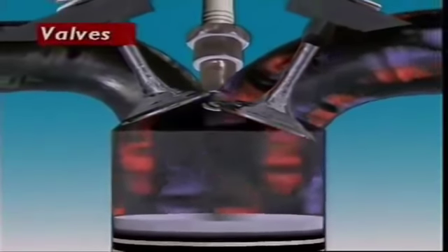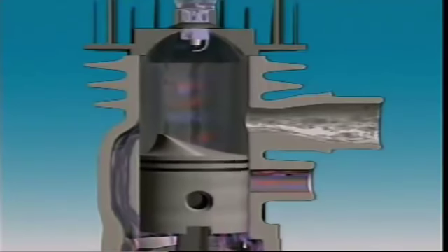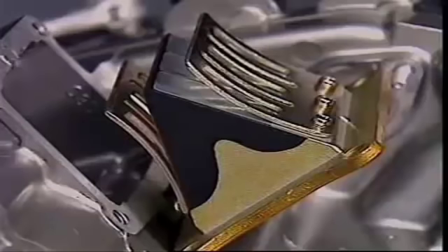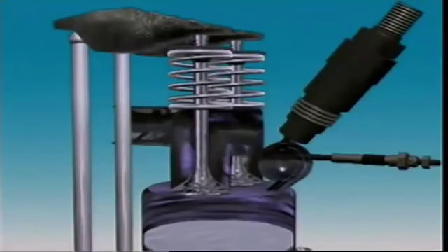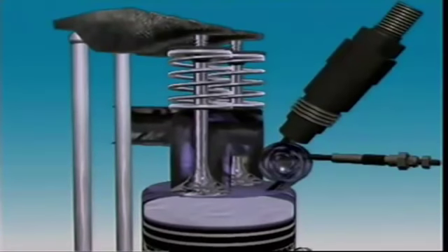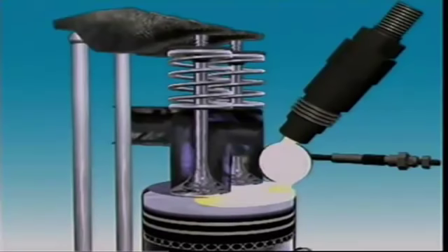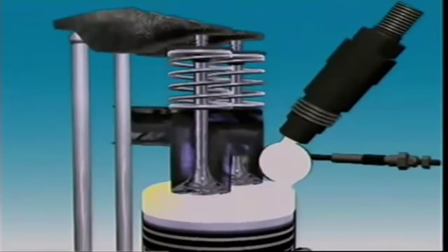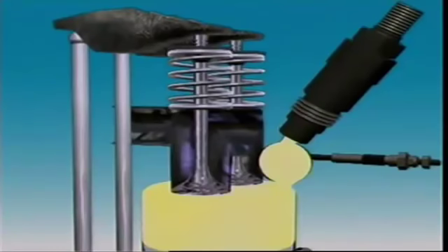This section examines valves. Petrol engines must control the flow of combustible mixture they take in and when it goes in. In small 2-stroke petrol engines, this is done by ports that are opened and closed by the piston skirt during the engine cycle, or by pressure-operated reed valves. Diesel engines are different. Their power and speeds are controlled by the amount of fuel injected, so it isn't necessary to control airflow into the intake manifold.